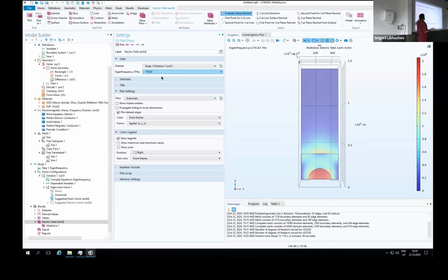the green one. What you need to do is to unwrap it, because of course the phase is between pi and minus pi, right? So there are these discontinuities, but you can just unwrap it and this is your phase. That's all you need. If you take the derivative with respect to the frequency, then you get the tau, you have everything.